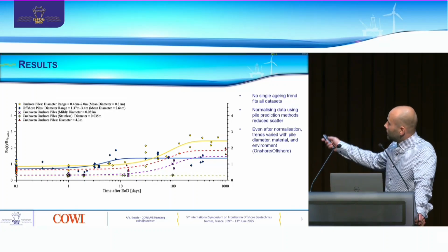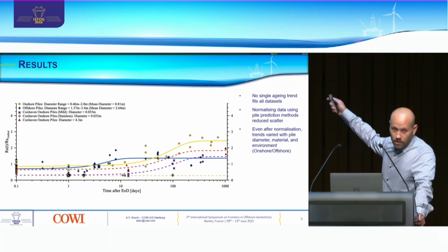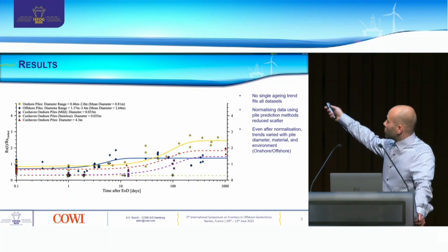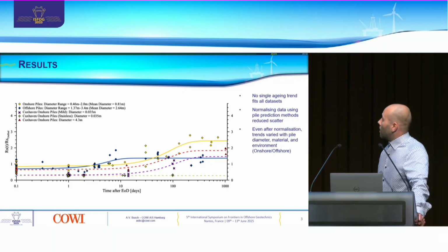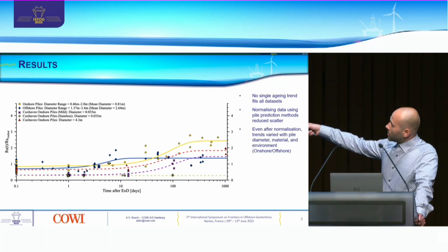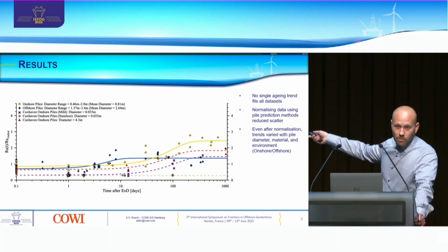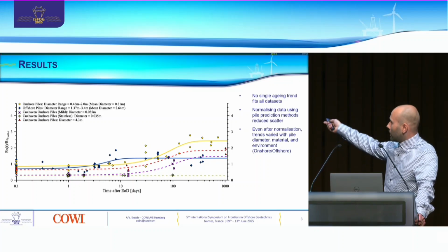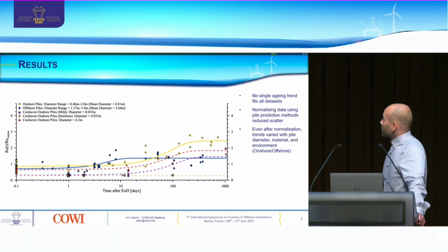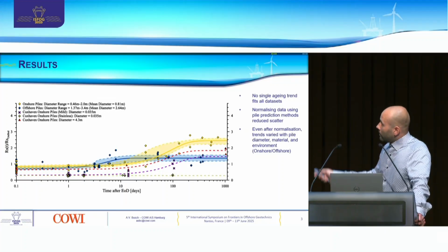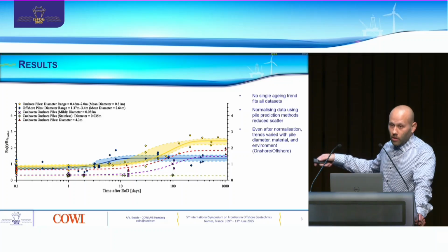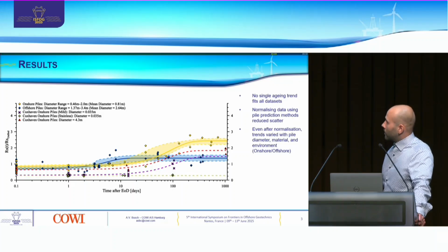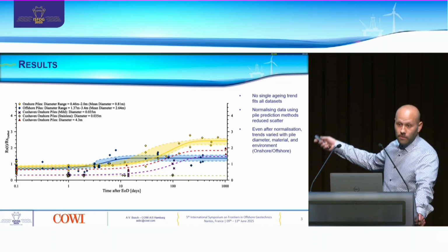We can see that, related to their predicted capacities, the onshore piles, the yellows, are at the highest, with the lowest capacities shown by the stainless steel micropiles, which are totally underpredicted all the time. We can even start using some confidence intervals. Here, an 80% confidence interval for the data sets where we have enough data points.